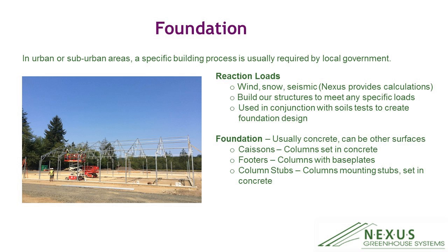A footer is when a foundation is poured around the perimeter to whatever depth it needs to go, and then the columns are typically attached to that footer. The footer may be 8 inches wide, maybe 6 inches wide, depends on what the loading requires. The columns are then attached to the top of that with a base plate, and you just drill holes through that base plate, and you use some sort of attaching mechanism like an expansion bolt to attach the foot plate to the foundation.